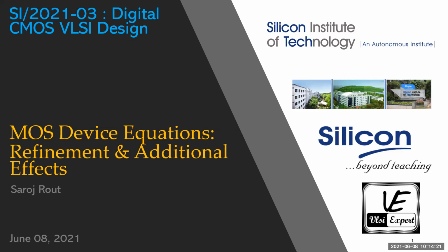In fact, most of what I'll show you are empirical solutions, or rather empirical fittings, because for most of these effects, there still doesn't exist physical equations for it. For example, even the velocity saturation and some of the temperature effects are empirical fittings in the model. So people just measure it and do empirical fittings into the models.